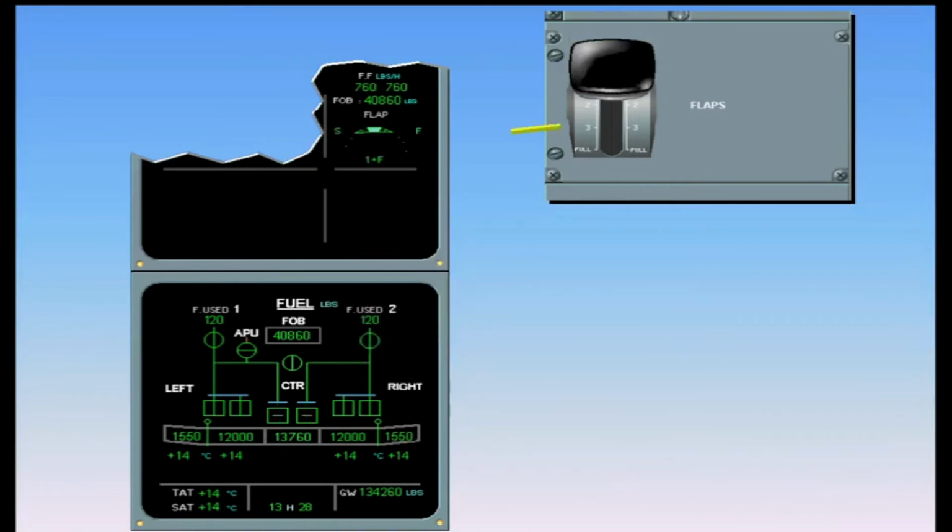Observe, the flaps are extending. 2 minutes after the second engine start, the message, Center Tank Feeding, disappears. On the ECAM fuel page, the center tank pumps are cross-line green, indicating that they have stopped running automatically. The main wing tank pumps now feed the engines for takeoff.